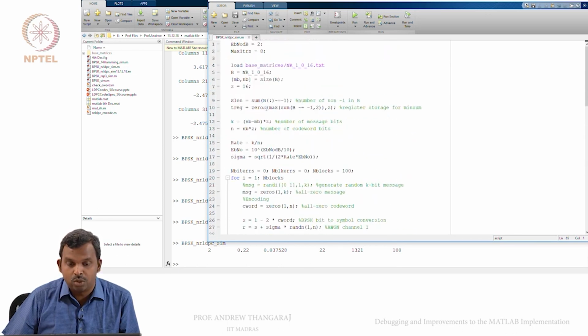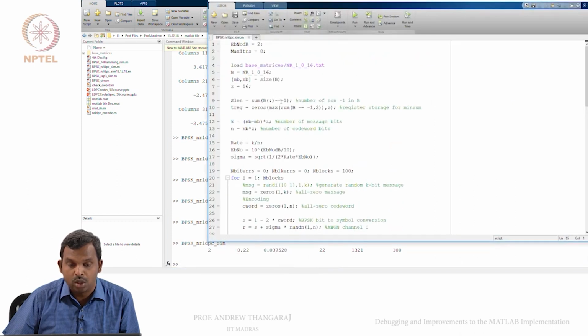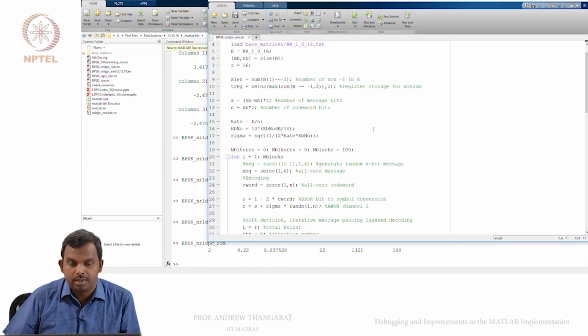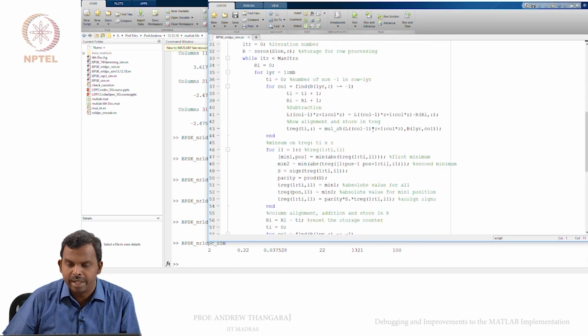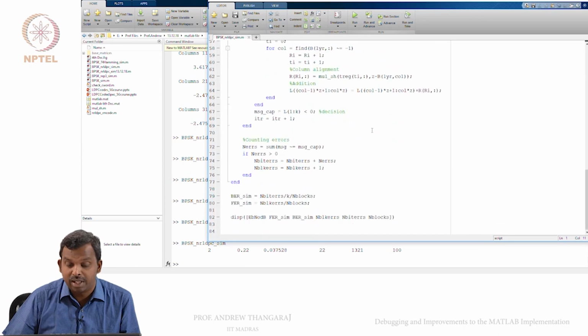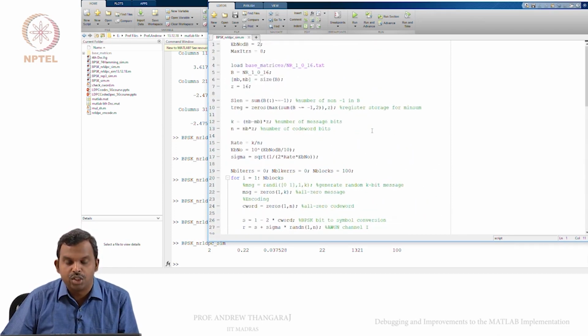So, this gives you a certain block frame error rate already at 2 dB, which is 0.22, and then slowly it will start falling at 3 dB of Eb/N0 and so on, to lower numbers. Okay. So, hopefully, this is expected performance. I am not sure if this is really good. I will have to check this, because it looks like this code should do something slightly better than this, but maybe the expansion factor is very low, but at least at high SNR it works. I will check on this once again, and it should be fine.